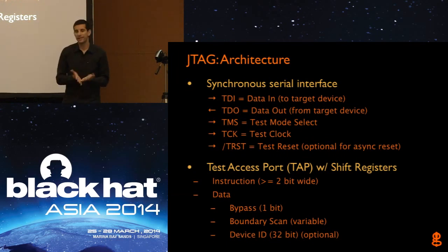There's an optional test reset pin that some target boards use to asynchronously reset the JTAG. Mostly they use it to disable JTAG, just by pulling the pin low to keep the JTAG port in reset so somebody can't just come up and attach to it.